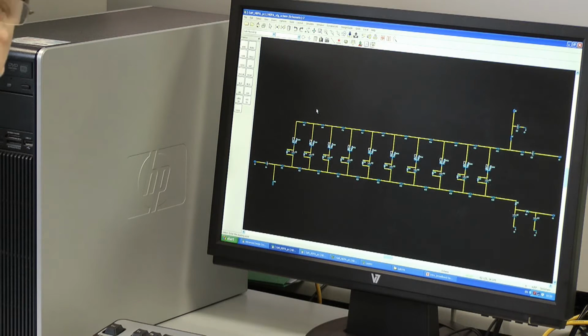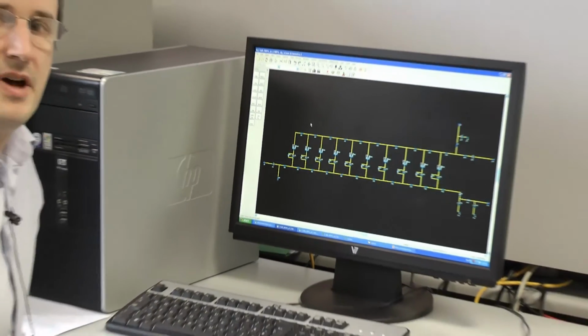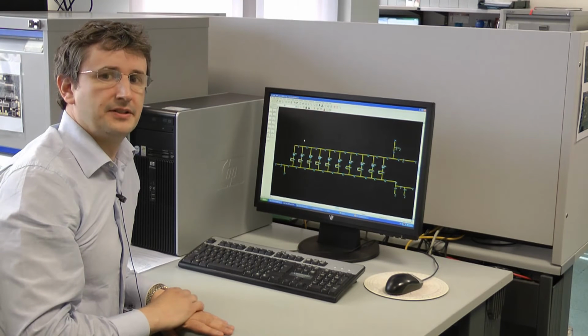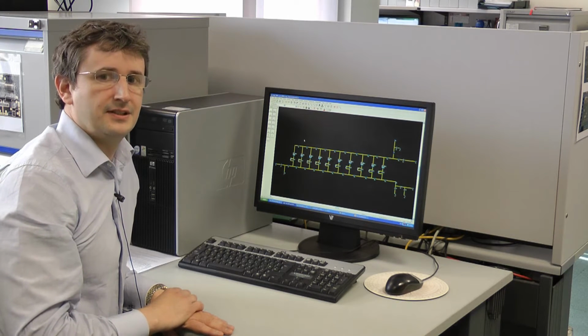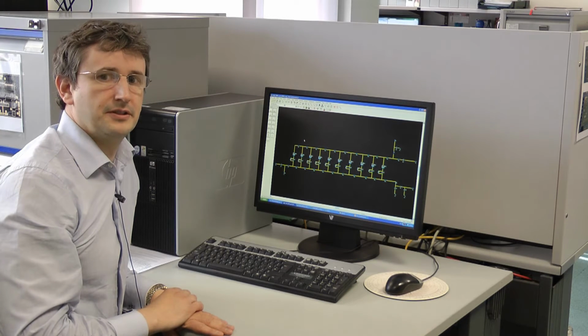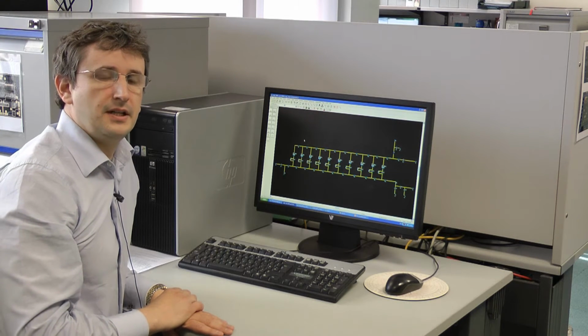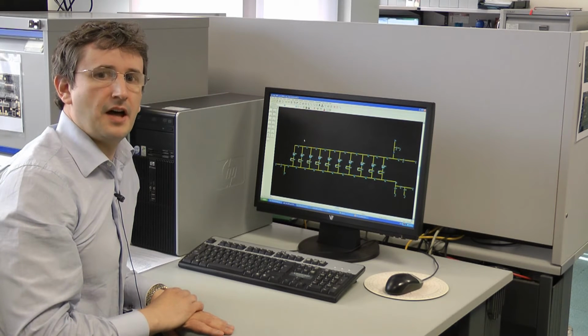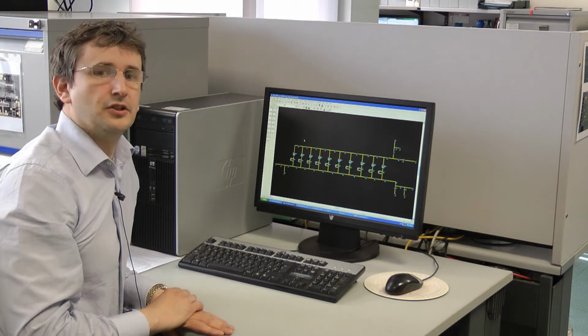Now, in a distributed amplifier, the upper operating frequency determines the maximum size of the common source devices. The main parasitic capacitances of the devices, that is CGS and CDS, are absorbed into gate and drain line low-pass filters. These low-pass filters are typically terminated in their characteristic impedances. Now, CGS is the larger of the two capacitances and determines the maximum size and hence output power for a given upper operating frequency.